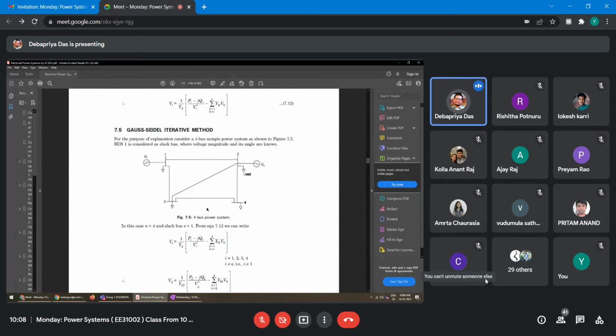So in any power system, whenever you solve such a problem, you have to assume that one bus is a slack bus, where voltage magnitude and phase angle are known. With respect to that voltage, the other network voltages will come, right? Generally in per unit, this voltage will be 1 per unit and angle will be 0. For the other buses, you have to compute voltage magnitude, phase angles, line flows, line losses, all of it, when load flow studies are done. This network problem will be solved iteratively, right? So this is load, this is generator.